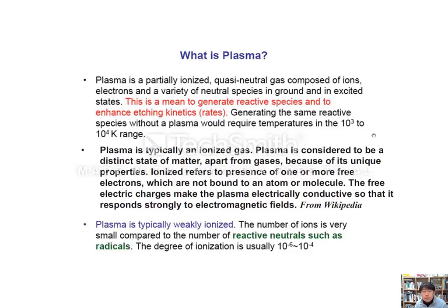High stress means low robustness and then low reliability at the end. A device under high stress cannot withstand the tough mechanical conditions in operation. So you really do not want high temperature in the process. That's where the plasma comes in, helping the process without high temperature.